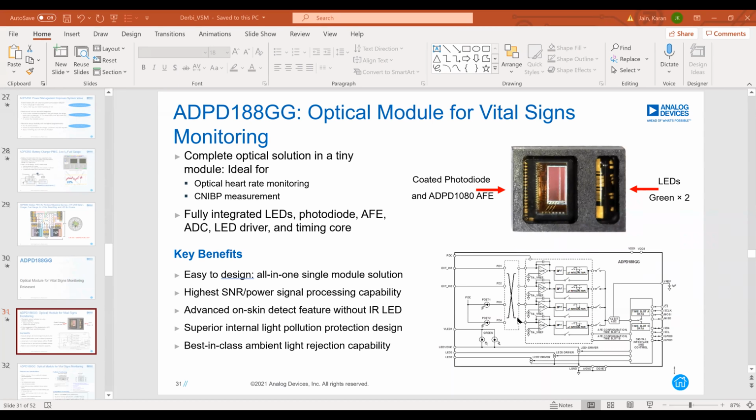If you start from the extreme left, you have these photo detectors, detector 1 and detector 2, which are the photodiodes, and then you have the analog processing for this, which is the transimpedance amplifier, filters, the integrators, getting into ADCs, all of it put together, and finally giving you digitized information. So this module would not get involved in any of the algorithm processing as such.